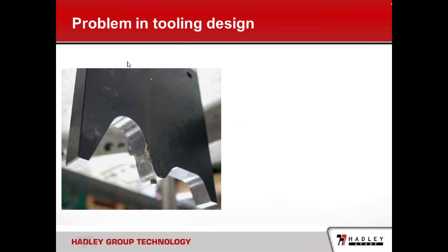In this case, what happened in production is that the shear plate, when it cuts through the channel section, creates some fracture and damage that we need to understand, and we need to redesign to perform this production successfully. As you can see, during the process, because of the very thick section, some fracture and damage developed in the shear plate, as you can see here on both sides, and also some at the top and at the bottom of the plate.